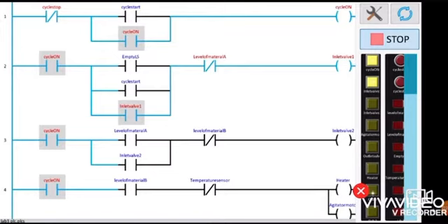If we turn off the empty level switch, the system is still going on because it is latched. In order to stop the inlet valve 1, the only thing needed is the level of material. When the sensor detects the material, the inlet valve will automatically be turned off, as you can see.